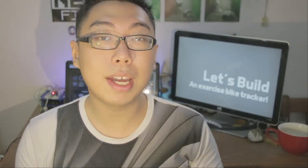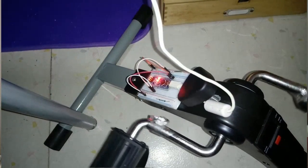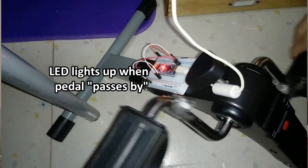So essentially what I've done is I've attached a magnet to one of the pedals and a reed switch somewhere nearby, right? Because we know for sure that the magnet is going to go around like this. And of course what that means is if at any point of time along the way we have a reed switch there, when the magnet comes close enough, it's going to close the switch. And that is going to, of course, send off a tick to the Arduino itself.